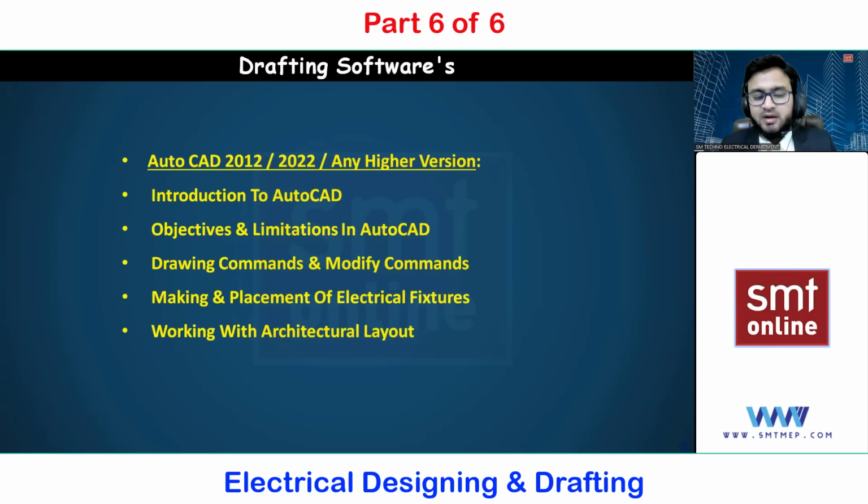When you go with electrical drafting, the first thing is to work with electrical legends. We are going to make and place some electrical legends. Once you work with these legends, we are going to place them on an architectural layout. This architectural layout you will receive from the architect department, your civil department, or your client will provide it. Once you have the architectural layout with you, you are going to work with the lighting layout, the raw power layout, as well as the air conditioning layout.